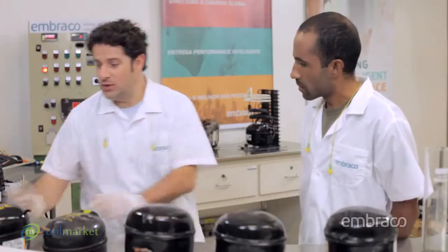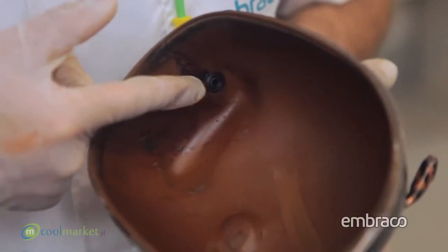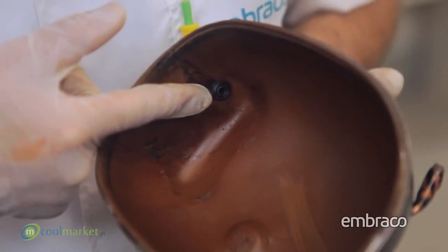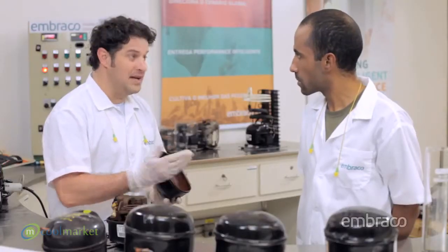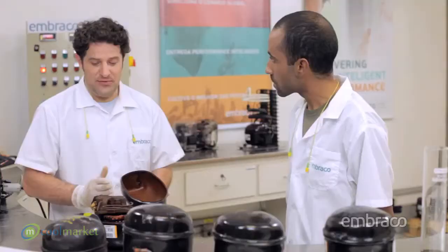Oh, besides these, is there any other way for moisture to get inside the compressor? Yes, there is, Mark, and this might happen with leakage in the product's tubing on the low-pressure side. When this happens, it's possible that air infiltration occurs in the cooling circuit through micro holes, and together with the air comes moisture. If leakage occurs in the high-pressure end, the problem will be identified with the loss of product performance. So Mark, have you ever seen the difference between a compressor with moisture and a compressor without moisture?